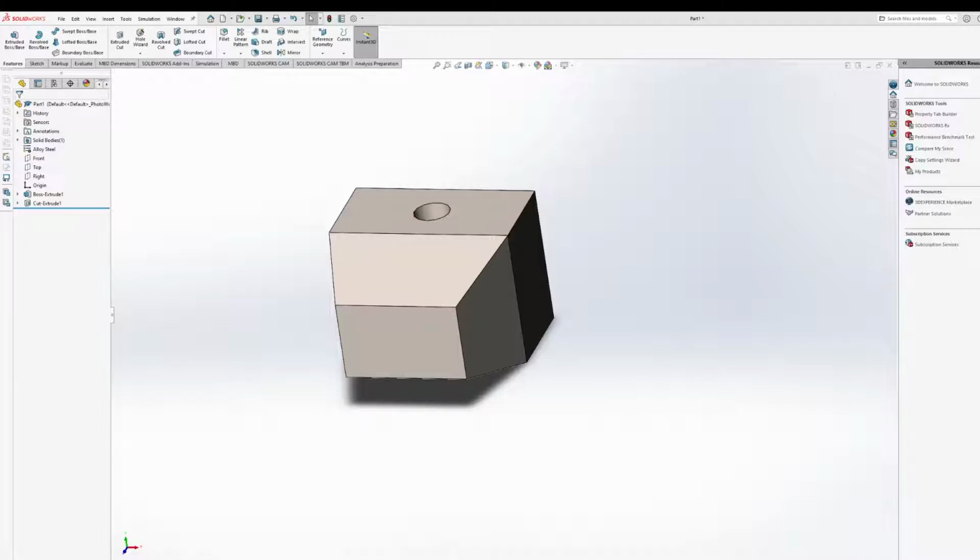Yeah. Okay. So you can use smart dimension outside of that on shapes that have already been created. Any of the shapes that you've already created, you can smart dimension them already. Sometimes it's a little bit finicky, but usually you want to just smart dimension your sketches, and that will kind of assign things properly.